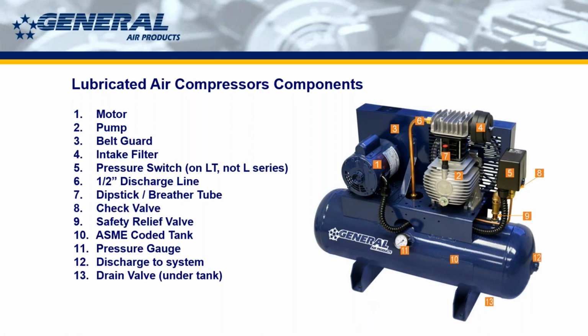When you compress air, you get water. And I think the number one thing that we get returned every year is pumps that the oil doesn't get changed in. But closer in that top 10 is units that get filled with water because nobody empties out the tank. So as a matter of maintenance, going in there and emptying the tank of any kind of liquid is vital to the success of these machines and their longevity.